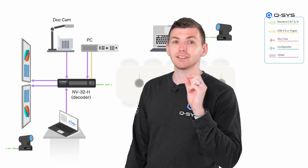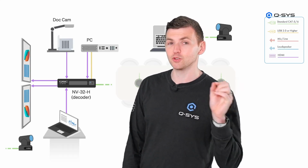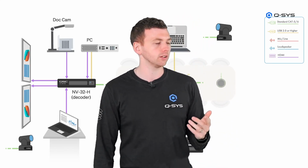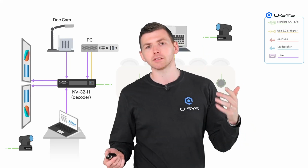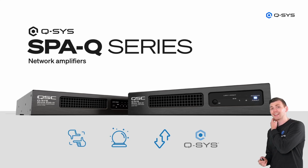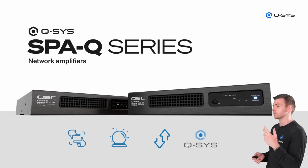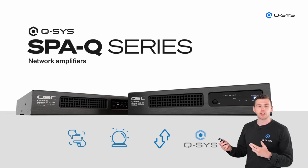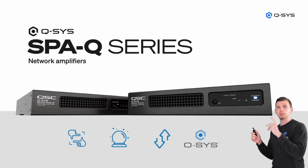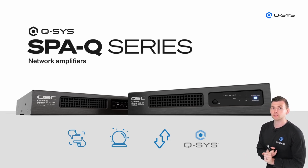That, by the way, is very cost-effective if you're doing like a mix-minus audio system where you do want individual channels. Actually, then NL is the best thing. But if you want a single channel, you're probably better off using passive loudspeakers and an amplifier. So let's talk about amplifiers. We've been making amps for over 50 years. Okay, that's what Q-SYS, QSC started out doing, was making amps. We've got very high channel count, high power amplifiers, but here we're just going to talk about the SPA-Q, small power amplifier, Q for Q-SYS, okay?